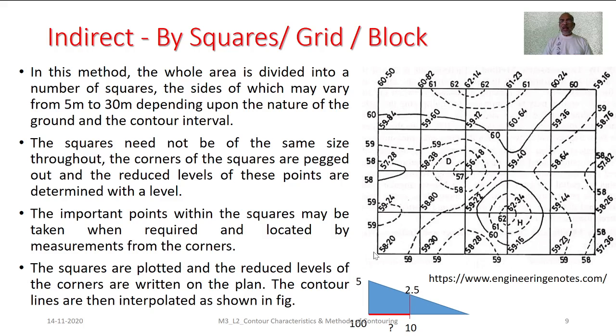So just for example, say here if this particular line is giving some chainage of 100 meters, let me consider this point as 100. So 100, left 10, left 20, left 30, left 40. So all those particular reduced levels will actually be determined.